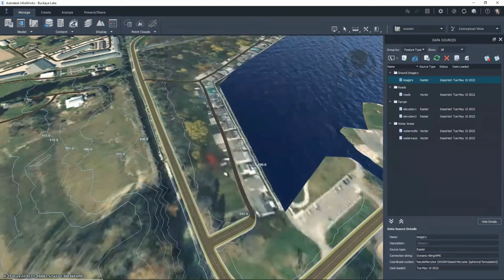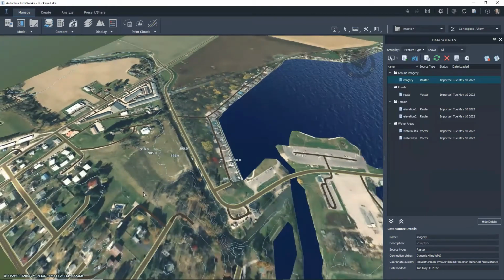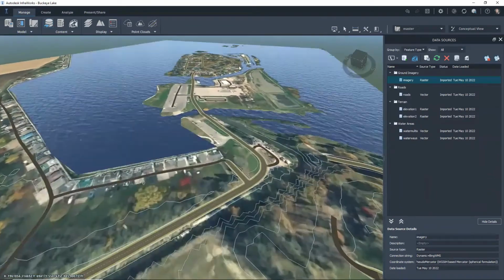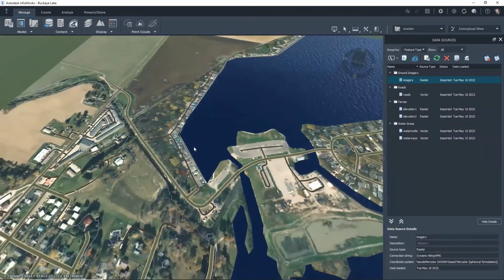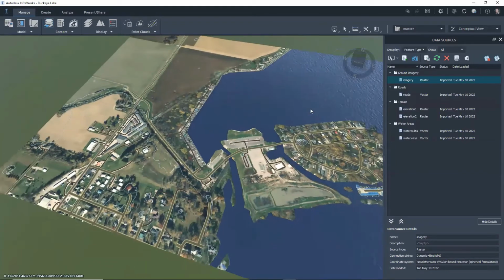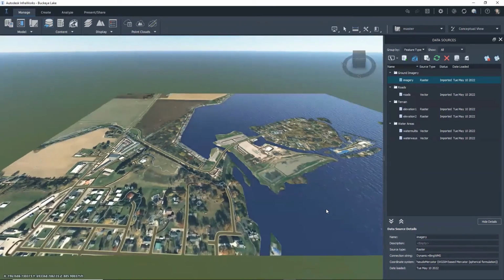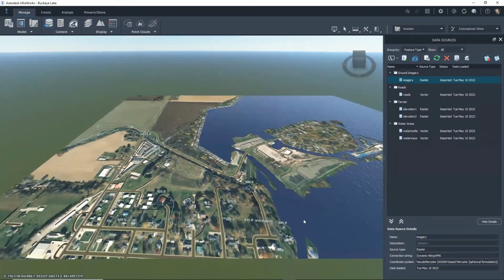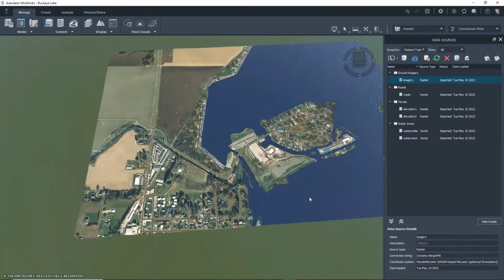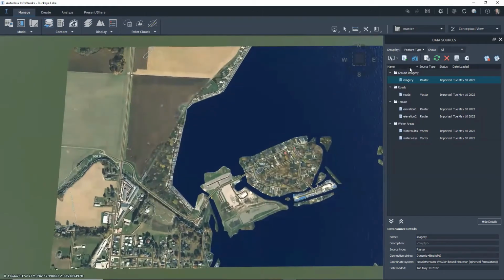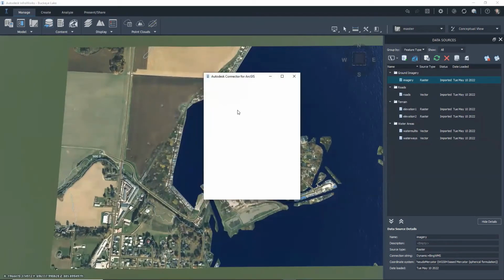I didn't change anything here, so I can just hit OK. But you'll notice that I don't have any buildings anywhere. And so there really isn't anything added to that. So I just have the terrain and the imagery and roads and water features. But how can you add buildings? Well, you could manually trace them, but that would take a while, particularly on bigger sites. But I kind of stumbled across this in playing around with InfraWorks a little bit. And they have this little button here called Autodesk Connector for ArcGIS. So, well, I don't think I have an account.